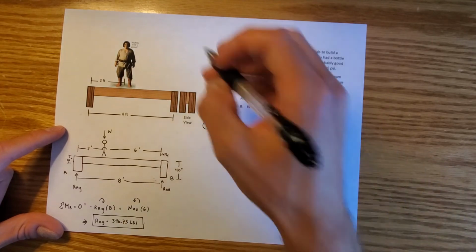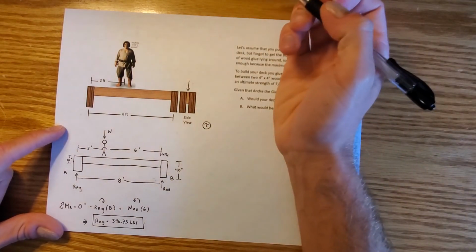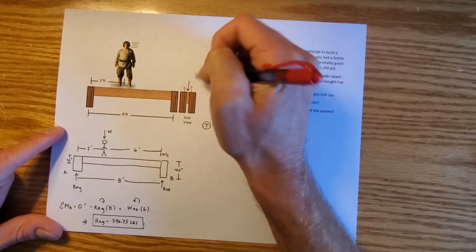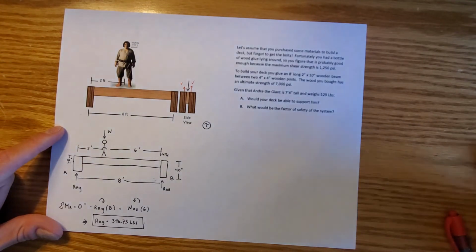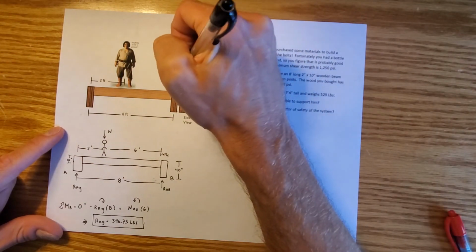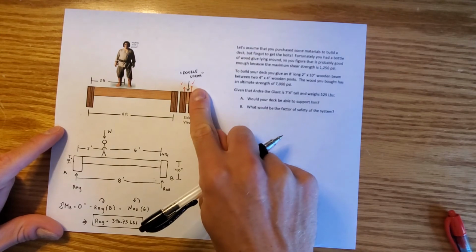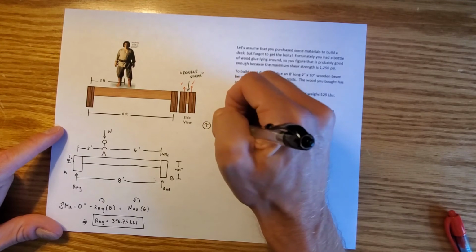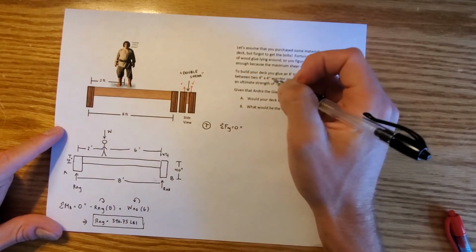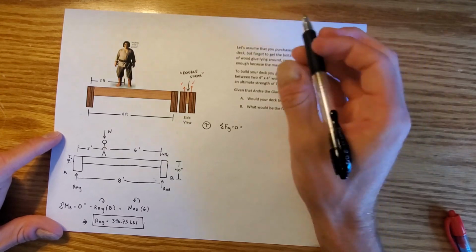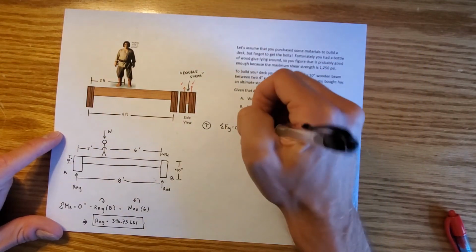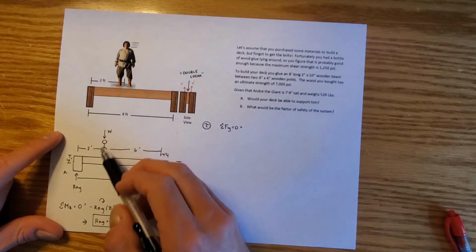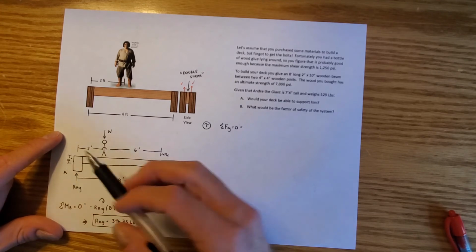Looking at our side view, what we can see is that the weight of Andre the Giant, pushing down here, is going to be fought by two forces inside right here at the joints. And again, this tells us that this right here is double shear. So if that's double shear there, then we do a quick sum of the forces in the Y. We set that equal to 0. And that's going to tell us that pretty much the downward force, which was the weight of Andre the Giant and RAY, because his weight goes down on the beam, but it's felt over here as RAY.